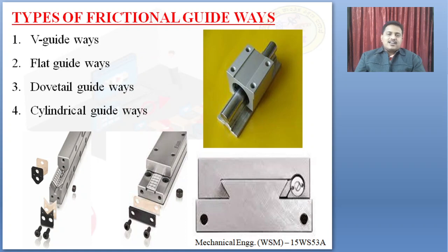Next is cylindrical guideways. These guideways are cylindrical in cross section. Basically you find this type of guideway in drilling machines, CNC drilling machines and some spindle attachments. Depending upon the requirements of the machinery, we go for different types of frictional guideways.